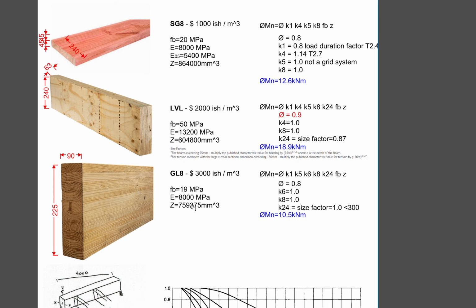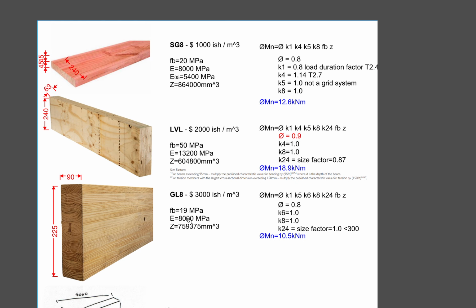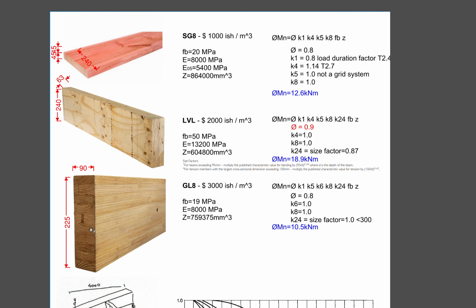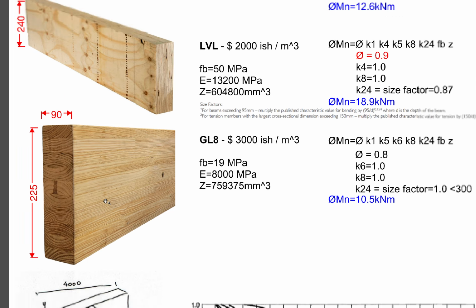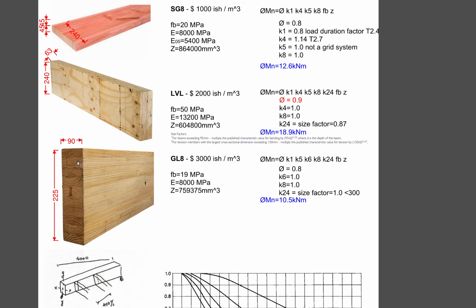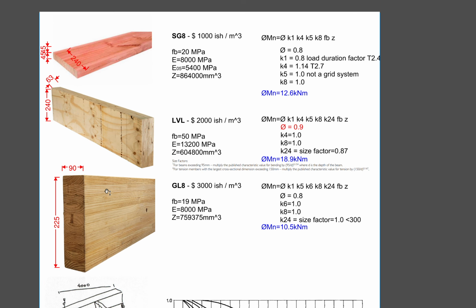And next, we come to the glulam timber. Glulam timber is just layers of sawn timber that have been glued together. In this case here, this is called a PLT because it's a parallel laminated timber. And you've also got a CLT, because you've got those timbers cross-laminated on each layer. We'll talk about that in the CLT design. So in this case, we've got 3 different types of beams that are mostly used in timber structure: sawn timber, LVL and glulam.